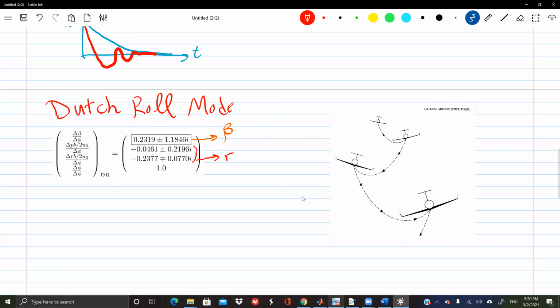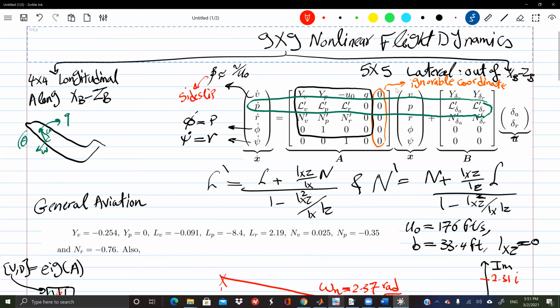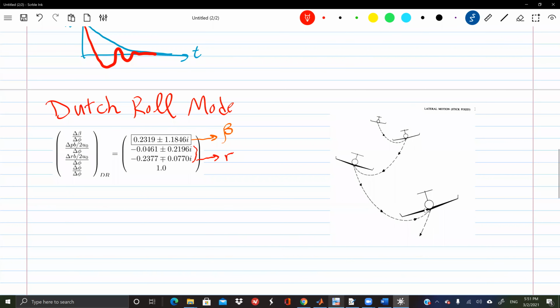So is this aircraft swooshing side to side, or is it losing altitude as it's also doing this? That's a very good question. It goes side to side, but also loses altitude. Whenever you roll, if you don't compensate, you will lose altitude, because what is vertical now is only part of your lift, not the total lift. So if you didn't increase your lift by increasing the angle of attack or your speed, you will always lose altitude. But we're not focused on the altitude here, because losing altitude is really in the other plane. We're just focusing on the lateral motion, the out of plane motion.